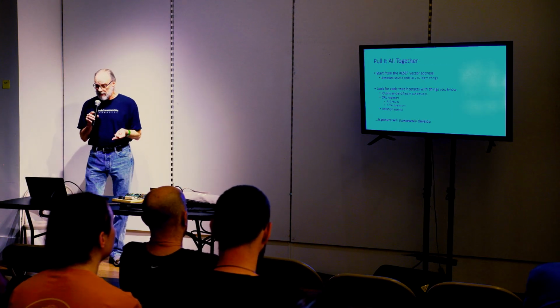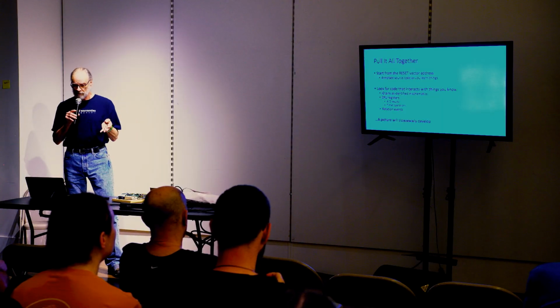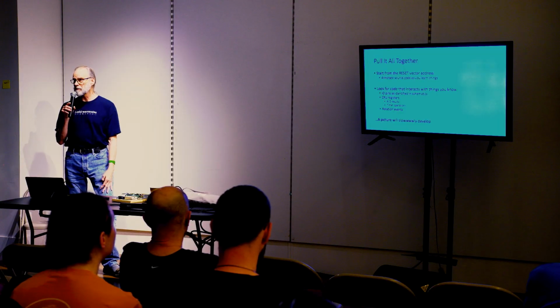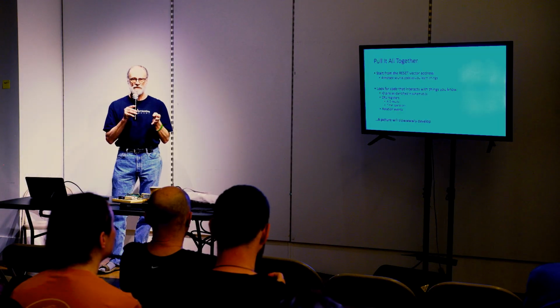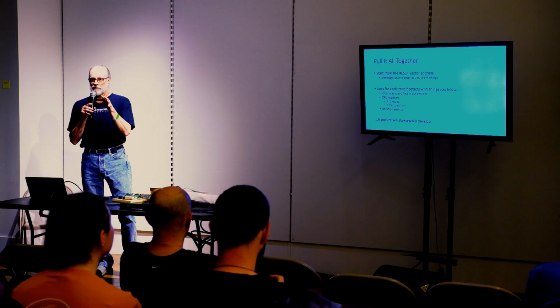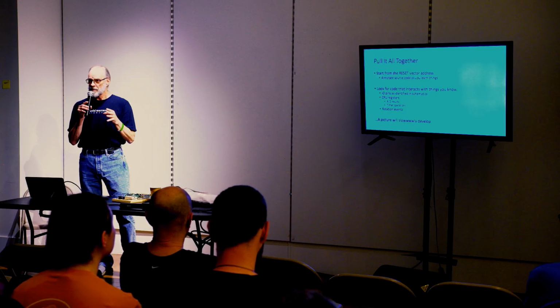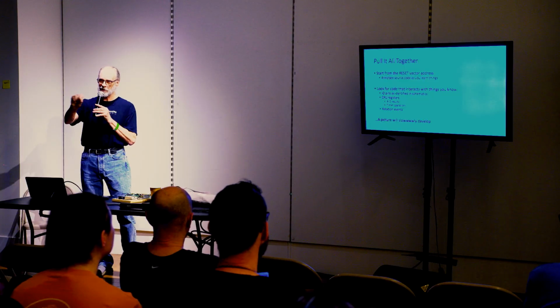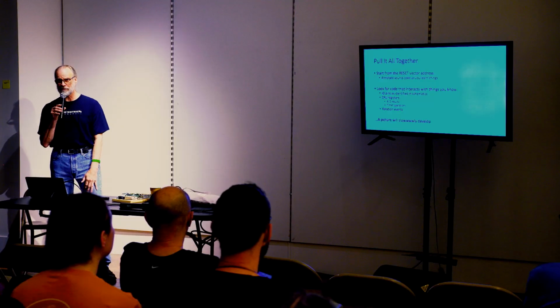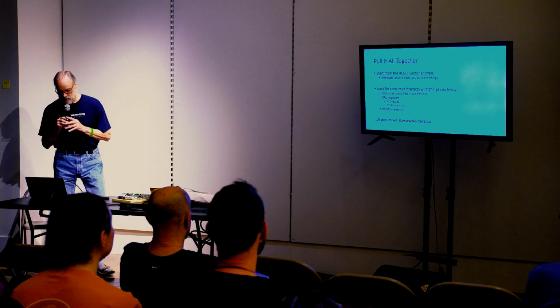So to put it all together, you start from the reset vector address, and you just start annotating the source code for what you can figure out. The good part is it starts off easy. You can see it pretty quickly do something like clear all the RAM. And so you go, ooh, clear all RAM, and it makes you feel good. Then you can start doing harder stuff, but you've got to start somewhere.